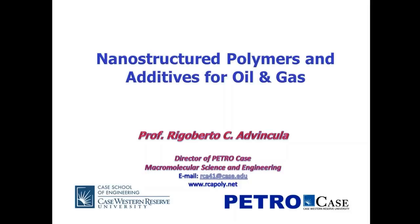Simply put, one of the paradigms we'd like to use in any coating for production is basically super hydrophobic and super oleophobic. If we can achieve both in a coating, then we can mitigate a lot of the scaling problems and deposition problems as well.